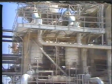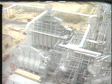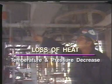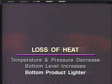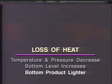Another situation that will cause a tower to operate abnormally is the loss of the heating medium to heat exchangers and reboilers, or the loss of fuel supply to furnaces. When the heat supply for a column is cut off, temperature and pressure inside the tower will quickly start to decrease. Less heat means that fewer vapors will be formed, so the liquid level in the bottom of the column will increase, and the bottom product gets lighter. Instruments and/or alarms will usually identify which piece of equipment has malfunctioned.